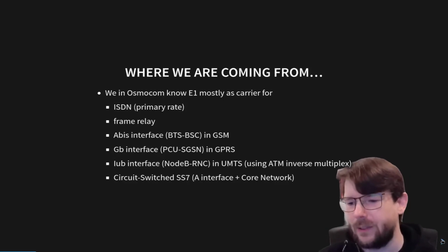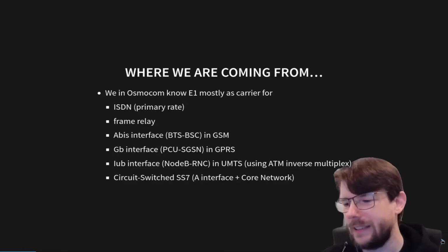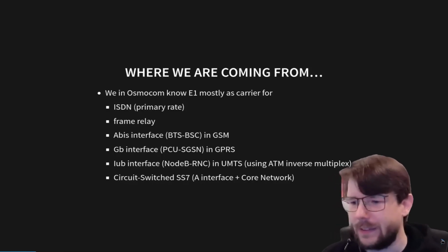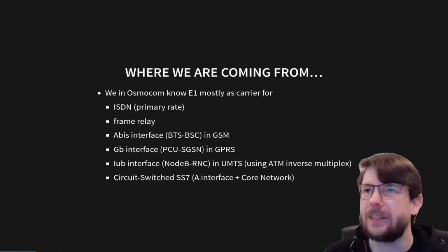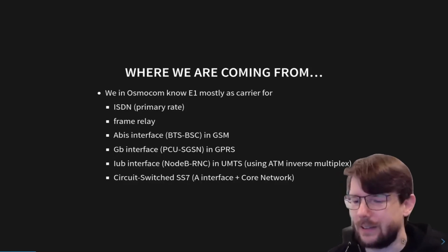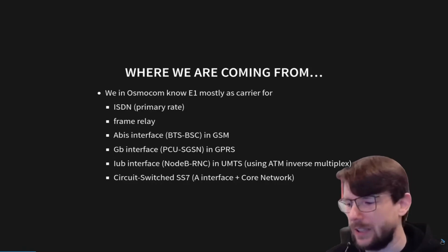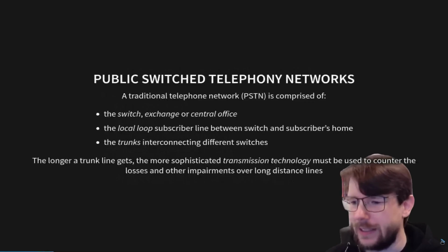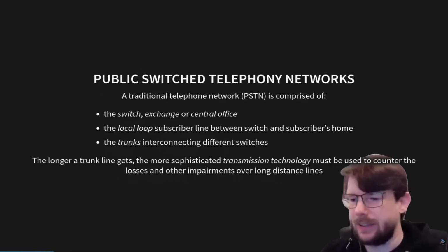What all of those, well, excluding frame relay, which is sort of an outlier, have in common is that we have the central channel signaling, not the channel associated signaling. So we have a dedicated time slot with a signaling protocol with messages on it that handles the signaling of the related calls or related protocols. Whereas today we will talk about the predecessor technology using channel-associated signaling and PCM30 technology.